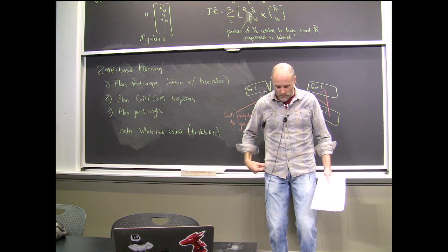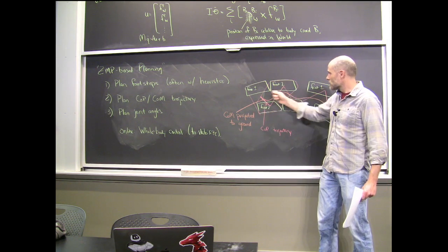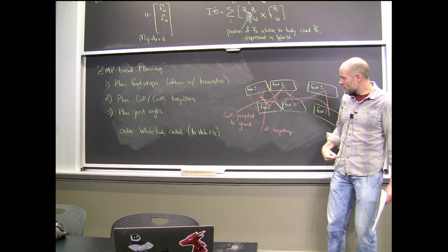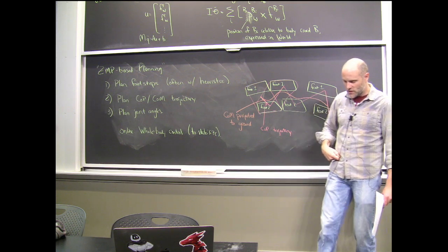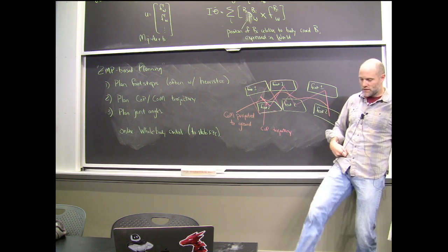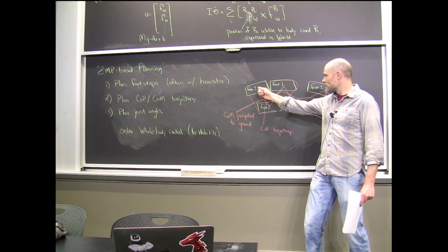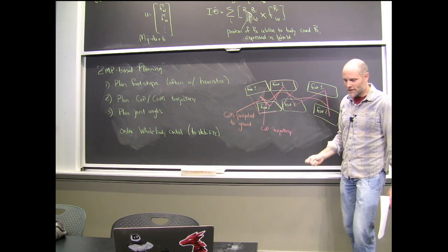Because what you'll do is, for instance, given this trajectory and given the timings, which are preordained at this step, I need to plan something that keeps my center of mass at a certain location over time and moves my foot to the next location over time. So we tend to make little parametric curves that take my foot from here to here.